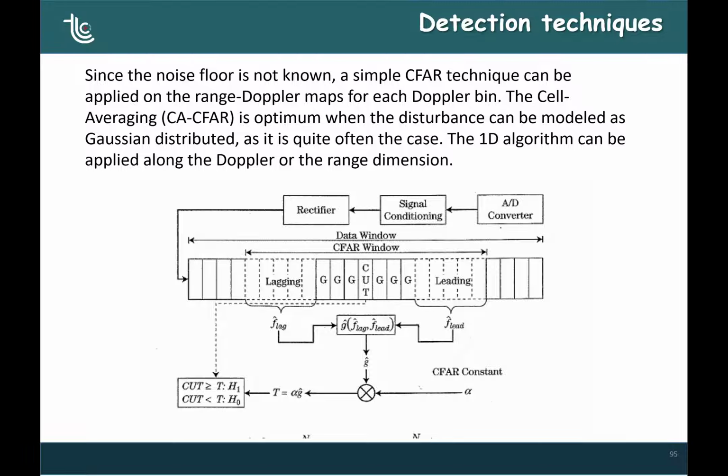And then let's go to the rectifier. The rectifier is a system that builds the modulus square of the entering samples, so the inputs, okay? At the input, we have the I and Q components of the range-Doppler map. Then we calculate the modulus square, and then we put it in a shift register.